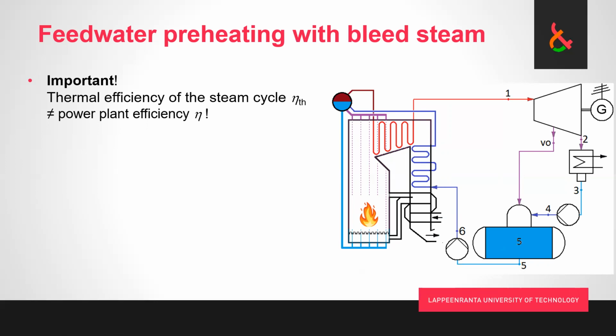Some recovery boilers, we are going to talk about that later in this course, and also so-called heat recovery steam generators in combined cycle power plants. For various reasons, you might not actually have this air preheater then. And in these cases, if you add more feed heaters here and you get a very hot temperature of your feed water, yes, the process efficiency of the steam cycle is going to go up.